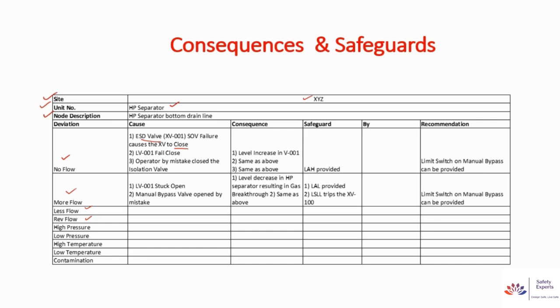So what will happen in that case? Level will increase in V001. Is there any safeguard for that? Yes, there is a safeguard. Level high alarm is being provided. So this will be a safeguard.